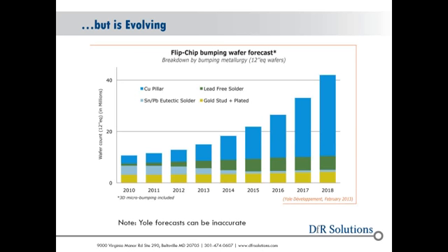Now, just to take a step back, and for those of you who need a little introduction, what do we mean by flip chip and copper pillar? What we're looking at here is a nice schematic done by my colleague, Dr. Gil Sharon, that shows you all the aspects of a flip chip interconnect. There's our die in gray, the silicon. And here's our substrate, for example, part of the BGA, which is down here in brown, and the various interconnections in between.